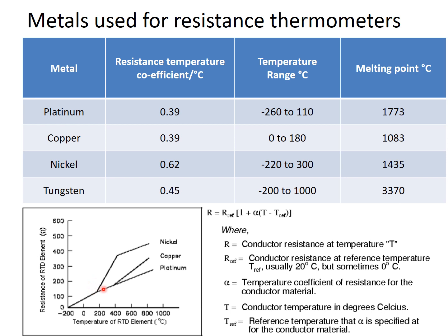Now look at the nickel characteristics. Nickel is most preferable if the resistance ranges between 100 to 450 ohms, so we can prefer nickel. If the resistance value increases beyond 450 ohms, nickel is not preferred. But the most preferable and stable metal chosen for RTD is platinum, because it has a stabilized waveform even as the temperature increases. The resistance does not rise suddenly. You can see the graphical representation here: it is a smooth variation compared to nickel and copper.